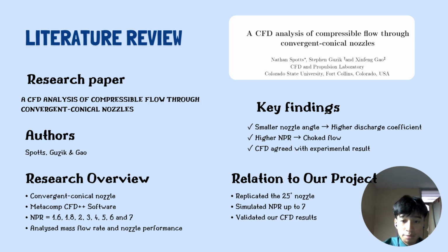The research paper that our group selected is entitled CFD Analysis of Compressible Flow Through Convergent Conical Nozzles by Spotts, Guzik and Gao. The researchers investigated compressible airflow through a convergent conical nozzle with a cone half angle of 15 degrees. They performed CFD simulation using ANSYS Fluent while varying the nozzle pressure ratio, or NPR, at 1.6, 1.8, 2, 3, 4, 5, 6, and 7.